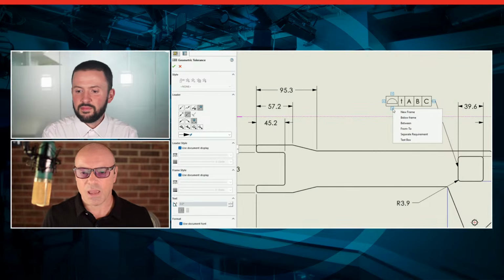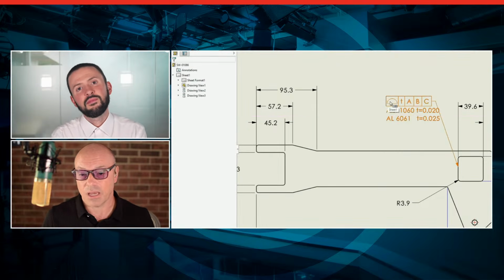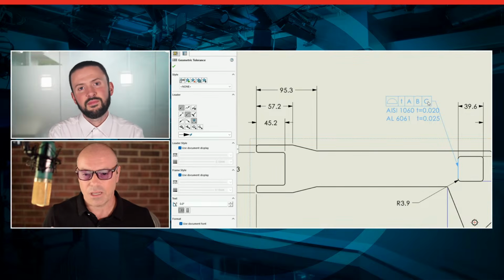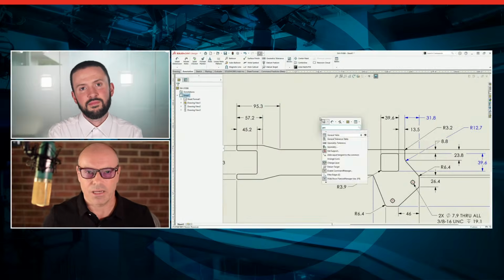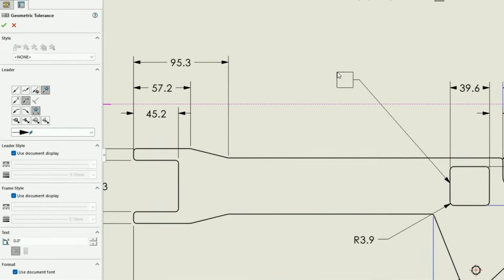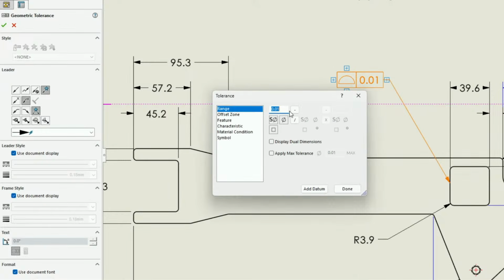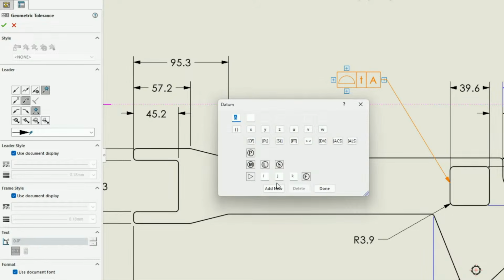This might be a case where you have a tolerance value that varies by material type. So we just put in a letter value, and now we can call out in either a note, a tolerance block, or a table what those different letter variable values are. So we can now put any combination of numbers, letters, or symbols in that range field.